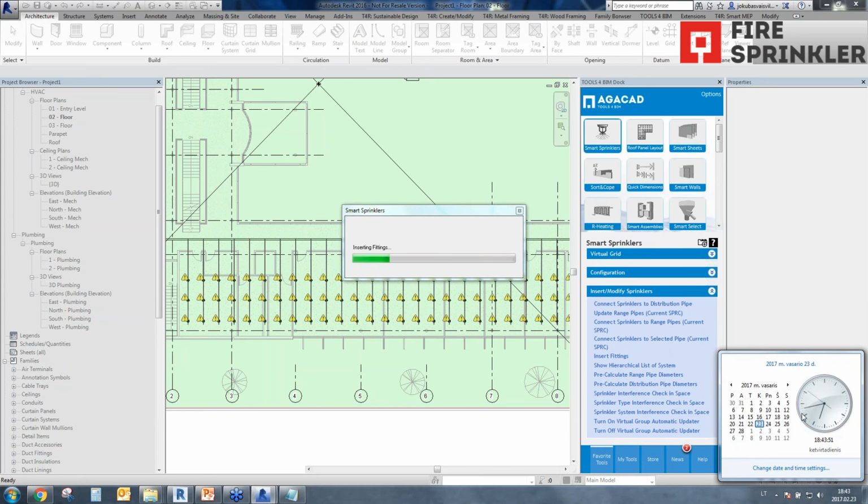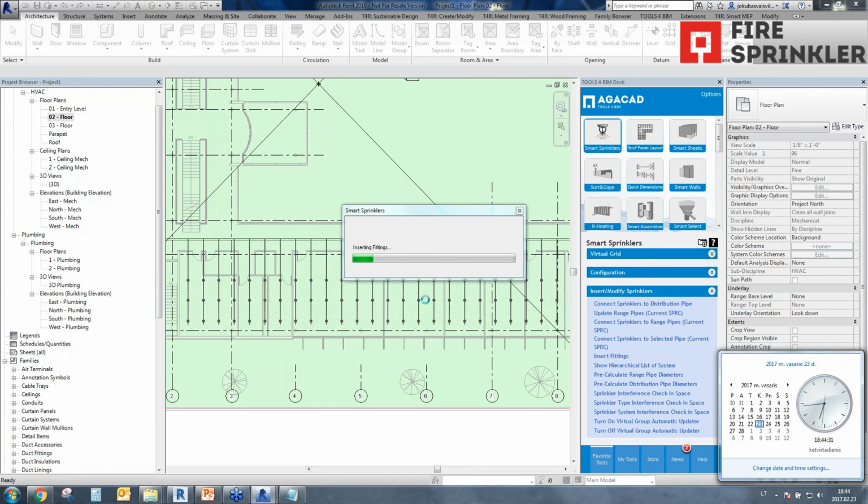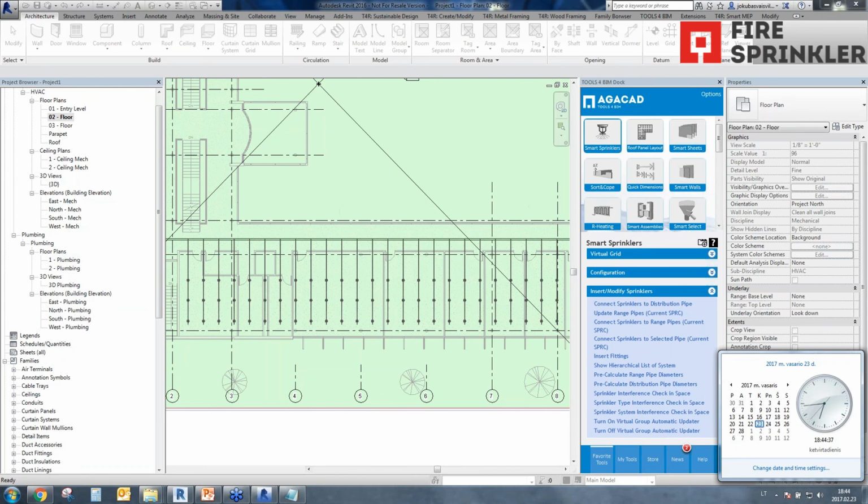It's not super powerful and speedy stuff, but still I see a very big improvement in my workflows. So I would strongly recommend using this workflow in your cases, because it's easy. You just lay out your sprinkler heads and ask to connect them perpendicularly to the distribution pipe. It takes about a minute, but please just remember how many sprinklers and how many pipes we have here.